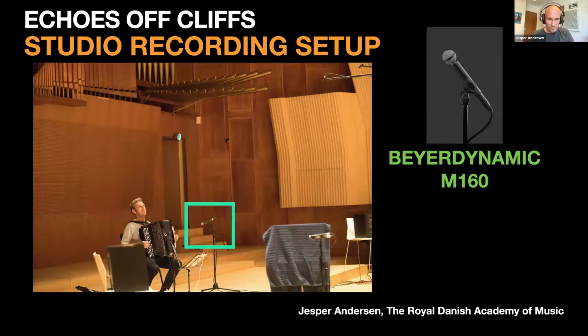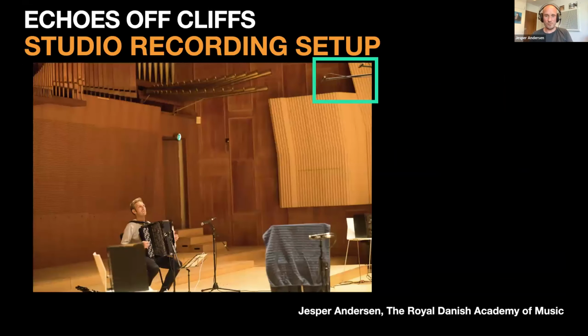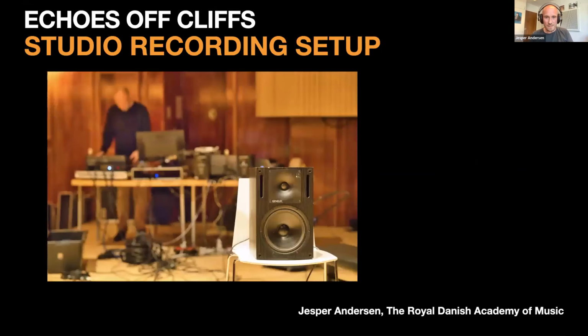We had some spot microphones on Bjarke. You can see pictures here as well. These are the Beyerdynamic M160. They are ribbon microphones. Everything else is captured with very high quality condenser microphones, but ribbon microphones for sitting like this have a really nice frequency spectrum that sits nicely inside a very high quality DPA condenser microphone. And these pictures are not so good. This is the main array, DPA 4006s.